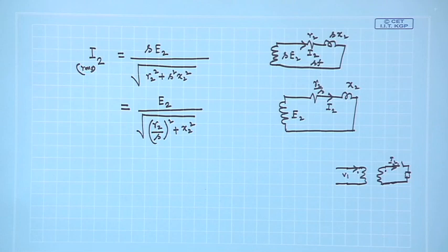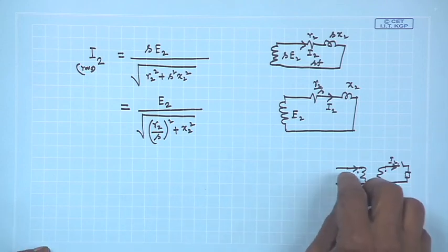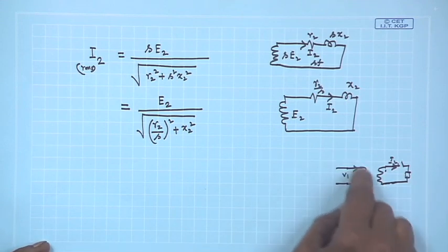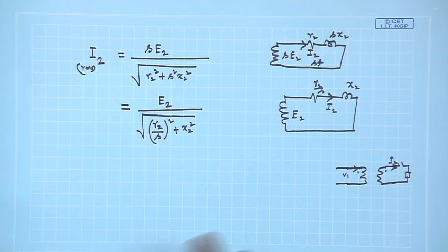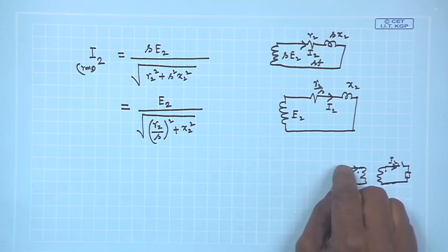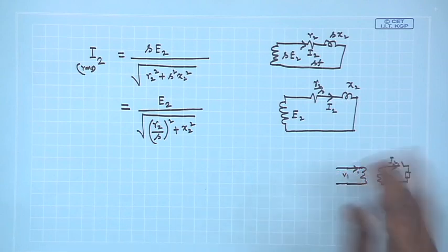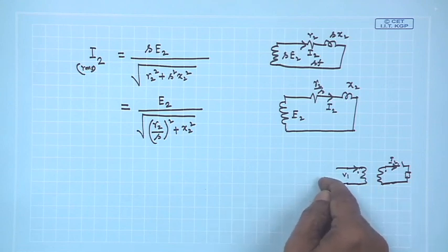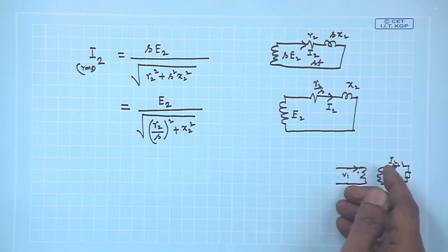Why can that not change? Because the supply voltage, the KVL is to be satisfied here in this winding. Applied voltage, small r1 x1, which suppose you neglect. So, the EMF here gets fixed by this V1, nothing doing.